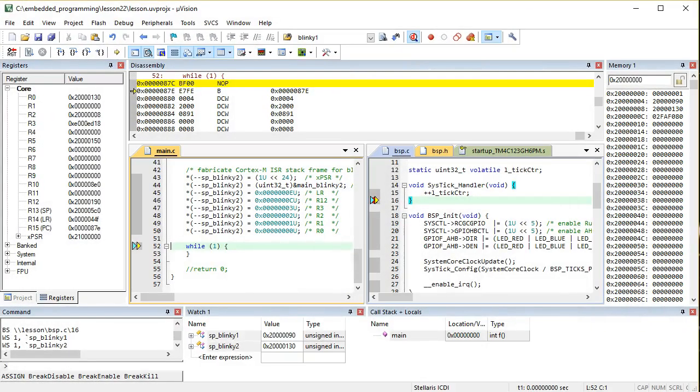All of this looks very promising as the way to implement the context switch, but you are not quite out of the woods yet. The remaining problem is that your context switch can still clobber some CPU registers, so the CPU state is not quite correctly restored before resuming a given thread. To understand why, recall from lesson 18 that the Cortex-M exception stack frame corresponds to the ARM Application Procedure Call Standard, AAPCS, in that it stores only the registers that are allowed to be clobbered by a function call, but does not store registers R4 through R11, which must be preserved by a function call.